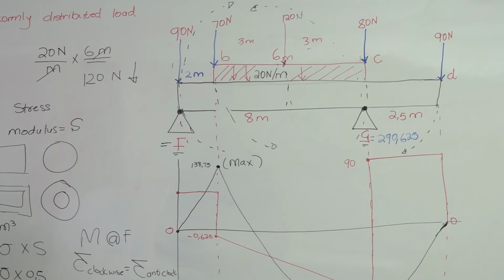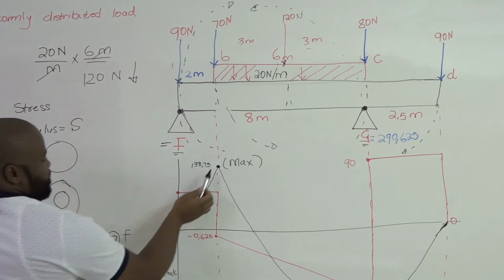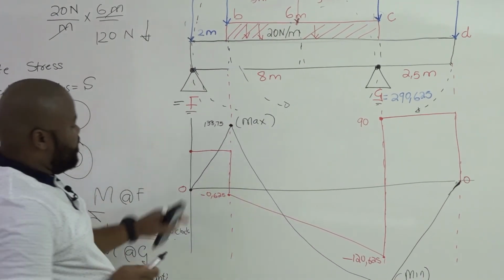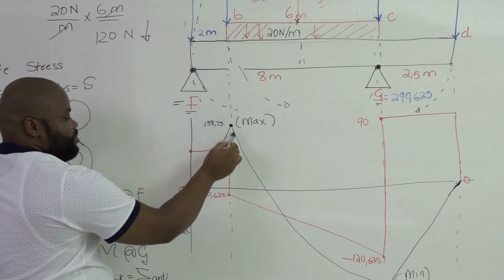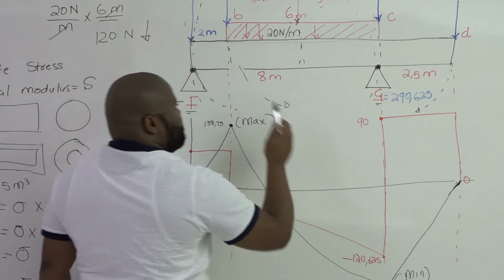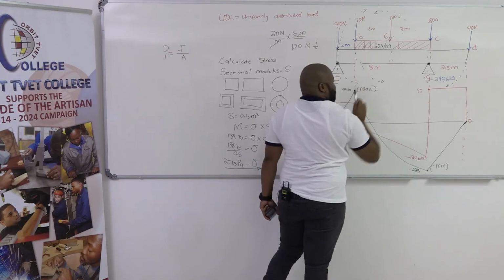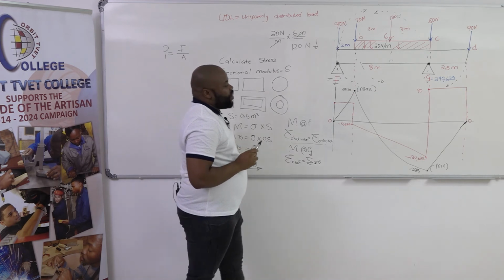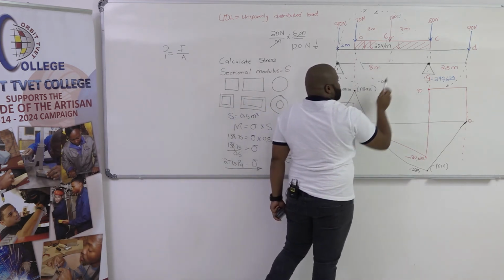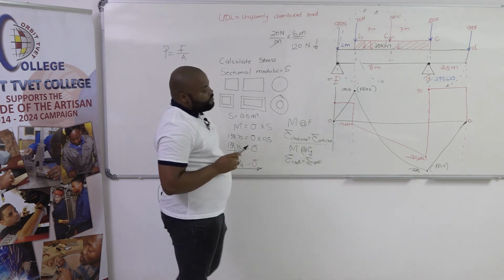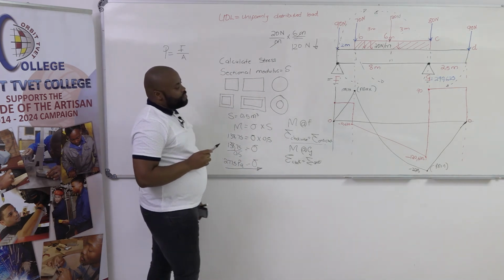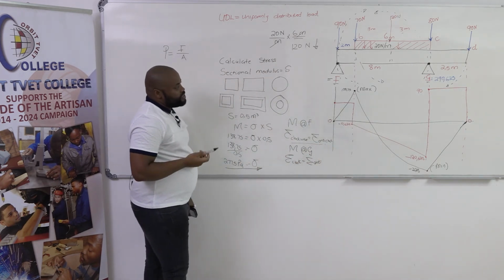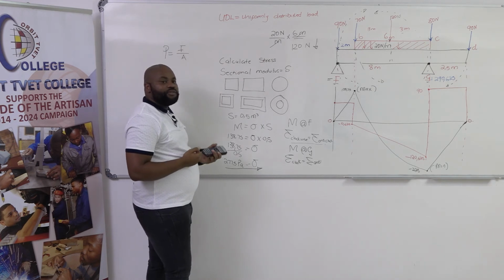The bending moment graph always slopes. If you have seen in our previous example, we slope everywhere, meaning that we're going to go in that shape, that shape, that shape, if we don't have a UDL. But because in this particular beam we're having a UDL, where there is a UDL, we're going to draw the shape of a parabola. That is the shape that we have used here. A parabolic shape instead of us sloping. That is critical information that you must remember.